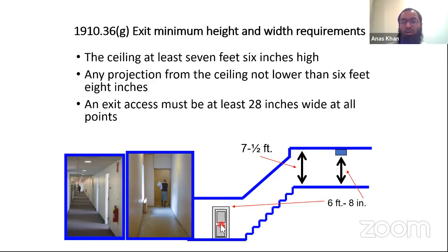And the size of your emergency exit door will be 6 feet 8 inches high. And the route itself should be minimum 7 feet 6 inches.